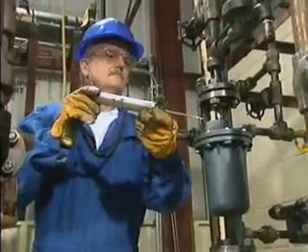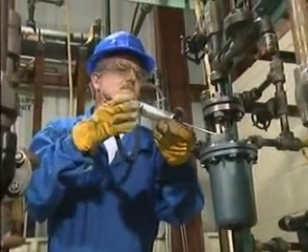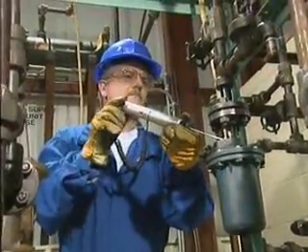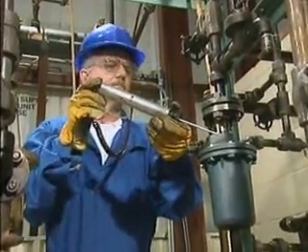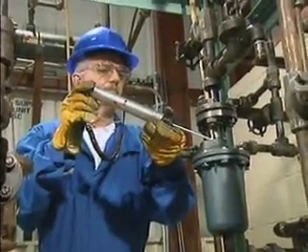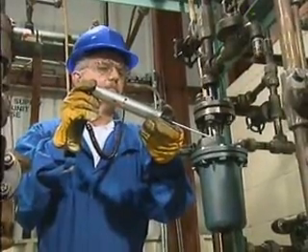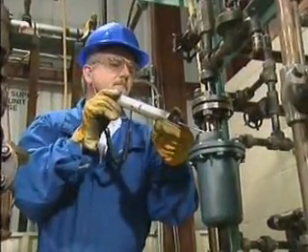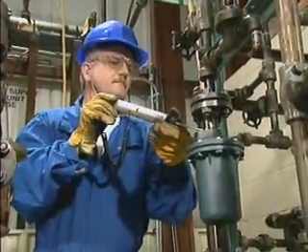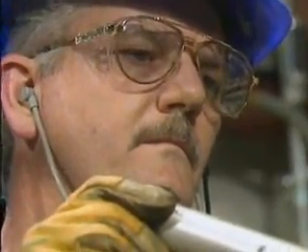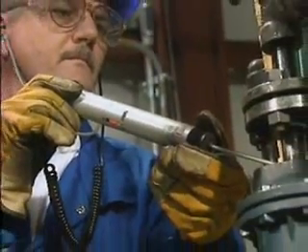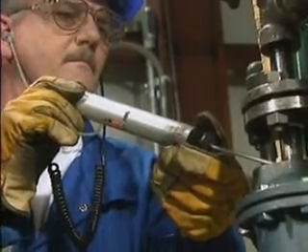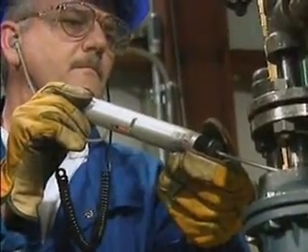Another type of trap inspection is a sound inspection. It's performed by listening near a trap's outlet for mechanical sounds and flow noises that are associated with the operation of the trap. To perform an accurate sound inspection, you generally need to use some type of listening device. The device carries the sound from the trap to your ear and helps filter out background noise from other traps, pumps, and similar equipment that can make it difficult to obtain a reliable reading.